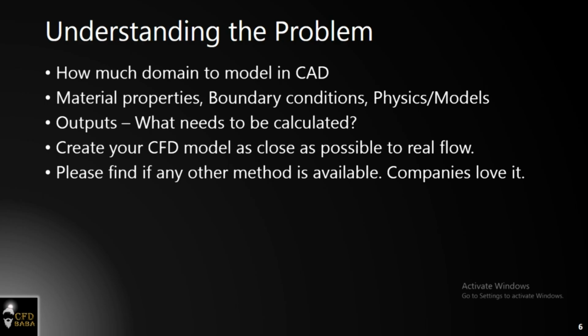And I would also say that a CFD model is just a virtual model of the actual problem. So try to create your CFD model as close as possible to the real flow. Another thing: if there is any alternative to CFD, then please use that method to solve industrial problems, because companies love it if you save some money. It can be done by creating tools in Excel using empirical formulas and so on.